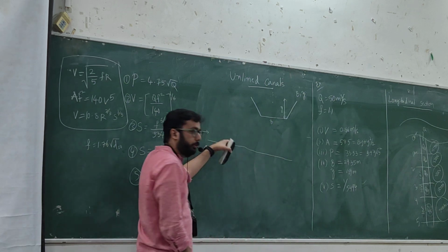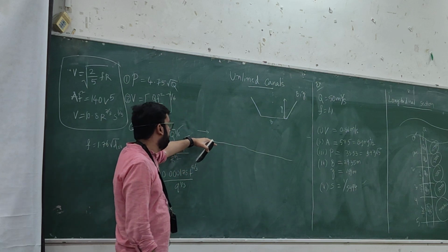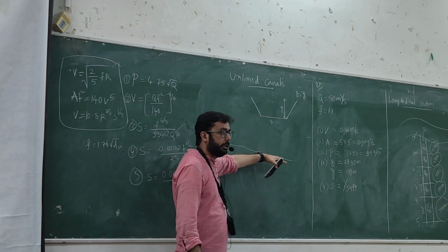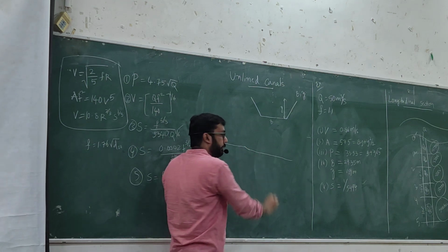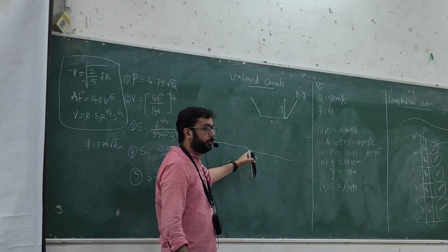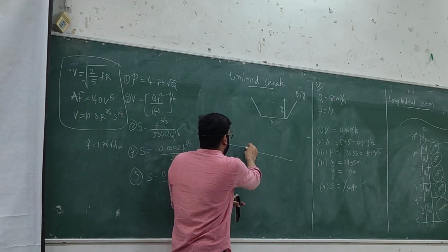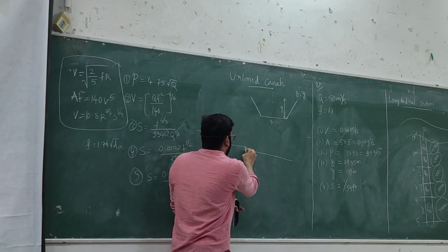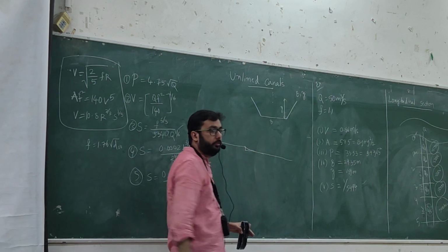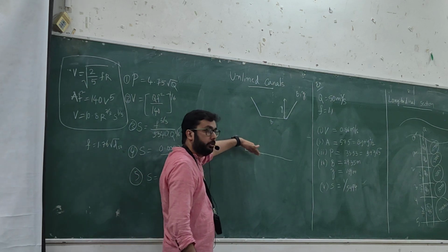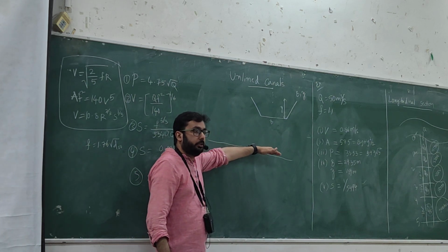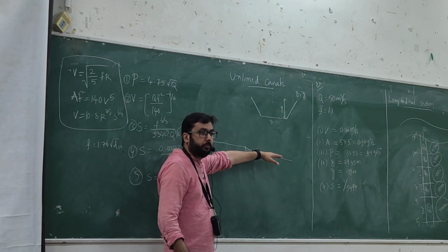Let's say this is the natural bed slope. At the entry, it is at higher elevation and it is decreasing as we go. But there is a sudden change in the elevation at some location. So here you need to design a section, and what we generally do is provide a fall. Instead of allowing it to follow the natural slope, you provide a fall, and then you let the channel follow the natural slope again.